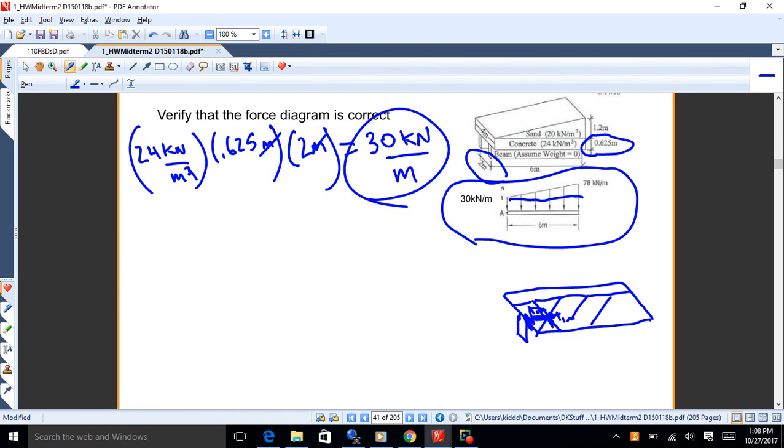You break it down first to an area unit weight by multiplying by the thickness, and then you can go to a linear unit weight if you multiply it by the width it's holding up. That turns that 3D problem into essentially a one-dimensional problem, weight per unit length.